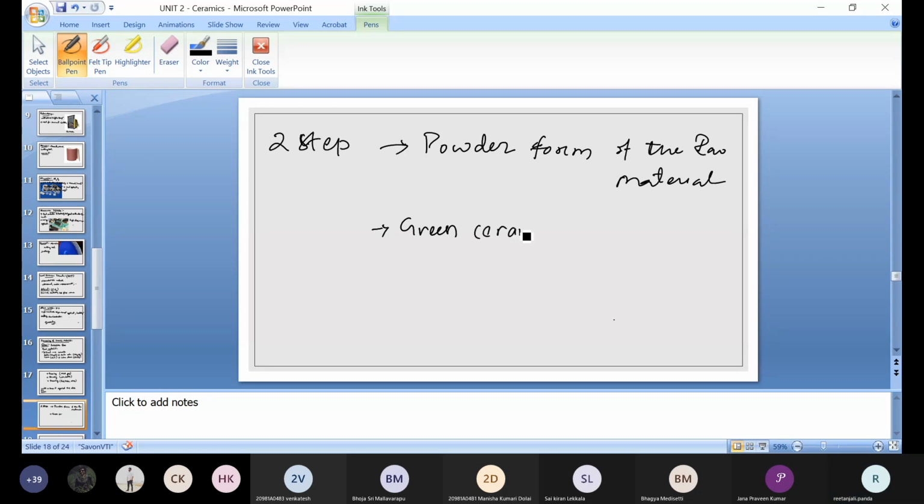ceramic. Okay, so if we are supposed to do an injection process, then after the injection process what we are getting is a green ceramic. Similarly, other elements, when they go through this manufacturing process, in the case of your polymer, the end product will be this green ceramic. Okay, this is one thing we need to know. Now, as I told you, this powder form which we are getting is by the process of grinding, milling, crushing; all those processes we follow to get these green ceramics.